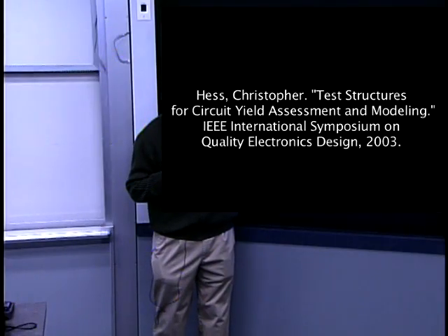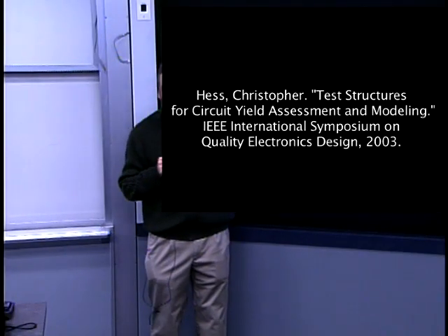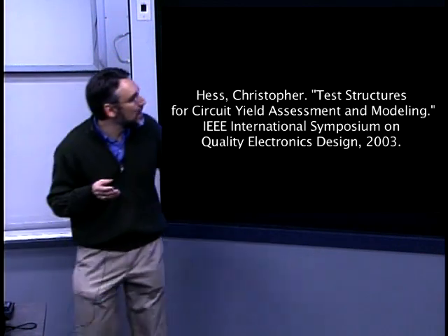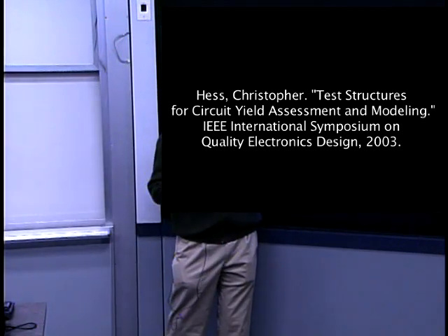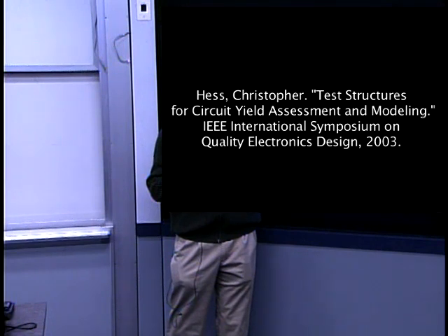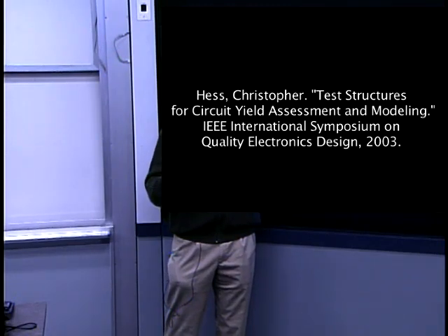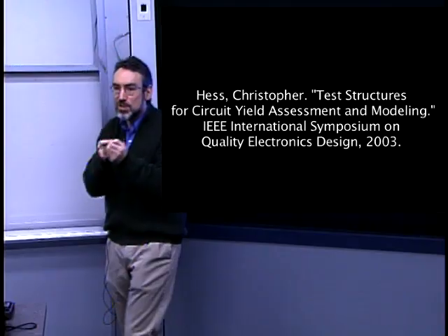What I mean by size is imagine that that little dust particle is only a quarter of the width of any of the minimum feature sizes on your structure. Well, that might mean I lose a quarter of the width of one of those metal lines, but at least it still conducts. It might have a slightly higher resistance than I expect, but functionally I'm still okay. Similarly, if it's too small of a particle to bridge between lines, I'm not going to have a short. So the idea is to control the particles down to a certain feature.